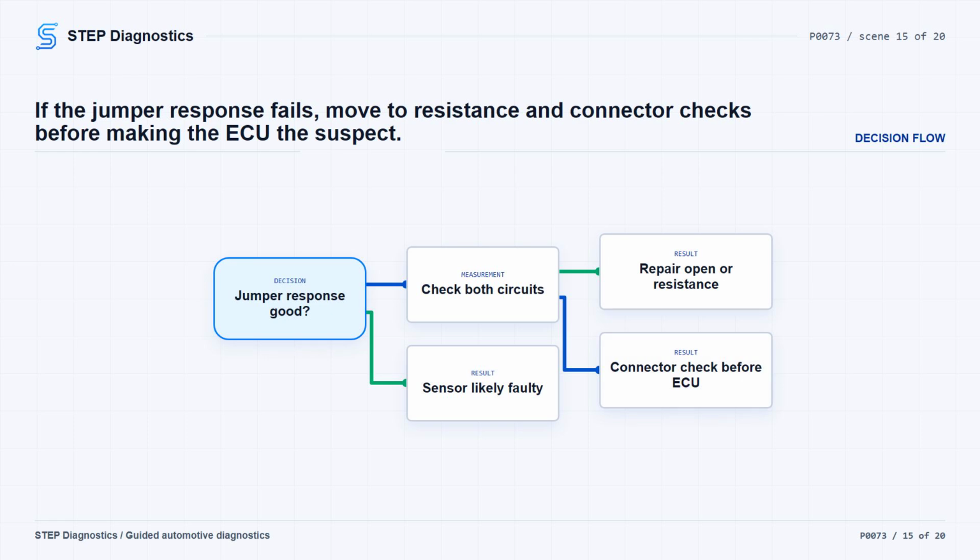If both circuits test good and the high fault is still present, check every connector in the circuit path for water, terminal spread, pushed out terminals, burnt terminals, corrosion, or dirt before condemning the ECU. If no issues are found, ECU replacement is supported by the diagnostic path.